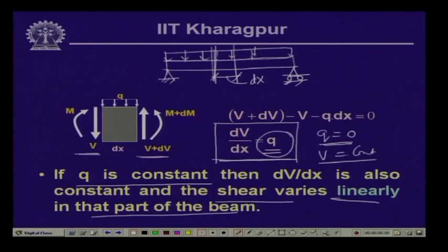And in fact, if you remember, for a simply supported beam with q as the uniformly distributed load, and since we do not have any horizontal force, the reactive force which we will have at the hinge support is a vertical one. If we call this A and this B, so this is R_A and this is again a vertical support, R_B. This being symmetrical, we can write that R_A is equal to R_B is equal to qL over 2, where qL is the total load. So, half the load will be carried by reactive force A and half by reactive force B.